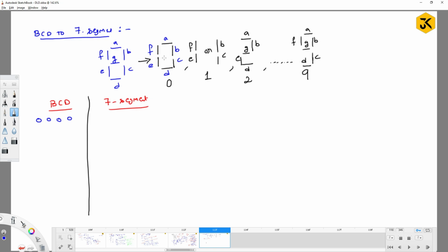So in this particular location, if I make the light bulb glow, it will look like a highlight. You can observe some kind of analog circuit somewhere. If you look at any olden days digital watches, you can observe this kind of thing. Fine. So if I give names A, B, C, D, E, F, G, what needs to be activated to get 0? A should be activated, B, C, D, E and F, and G should be 0. Right? This is the corresponding thing.